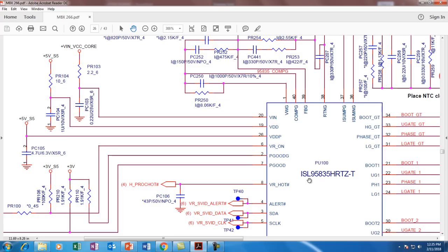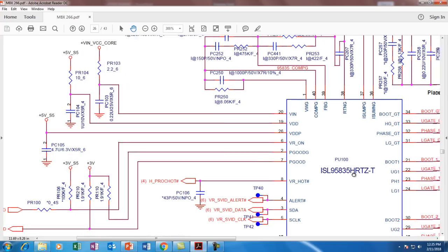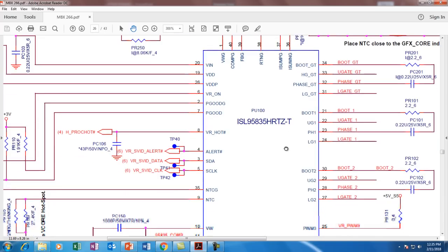The next signal required by this VRM chip is called the VRM signal. On this pin number 6, you should get 3 volt. In some latest motherboards here it is 1 volt. This VRM signal commands the VRM section to turn on. Once this VRM section receives this signal from the SIO, it triggers the PWM. There are 3 pulse width modulators in this chip. One is for the graphics, and these are the 2 for the CPU. This one, and another one, this.